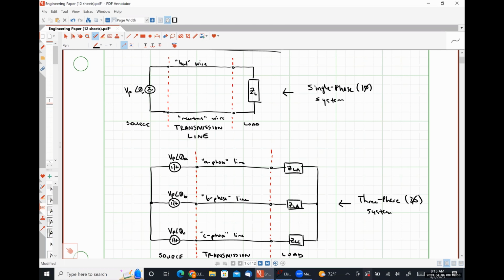What would happen if you tried to power an electric motor with power that was changing constantly? The speed of the motor is going to change constantly. The torque being developed by the motor is going to change constantly. So effectively, your motor is going to vibrate, and those vibrations are going to decrease the lifetime of that motor.